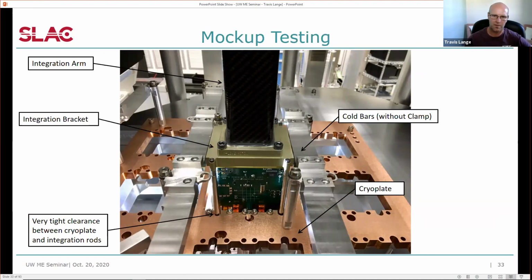So that is actually the surface which gets very cold during use of the camera. But it's also our mechanical interface for the Raft tower module. And so we are trying to raise up and bolt the Raft tower module to this cryoplate for both mechanical and thermal connection. And we couldn't have a lot of lost surface.